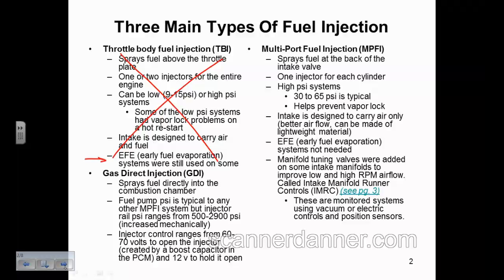I think that's where the biggest design difference is. If you're spraying fuel on the compression stroke, which you would be in a GDI at times, you need that pressure to be very high at the tip of a fuel injector. Some of our diesel engines, we're running 30,000 psi injector tip pressure because of the compression pressures that they're running. Turbo diesel with massive amounts of compression, ridiculous numbers. So our gas direct injection, we're not running that high of compression. We still need a spark to ignite our fuel. It's not compression ignition, it's still spark ignition.